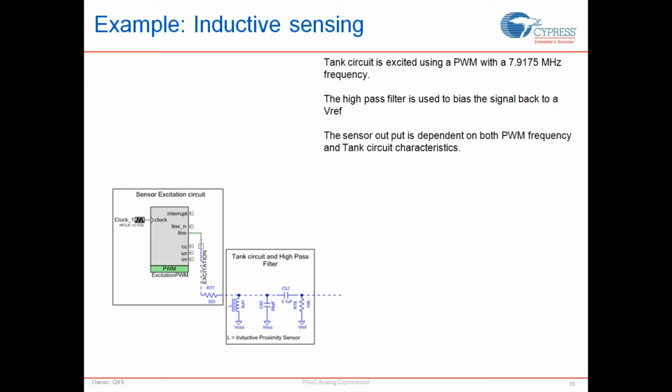So I want the variation from the 8 megahertz signal to be as minimal as possible, so that my down-mixed output is a really low frequency that I can measure using my ADC in an averaged mode and still get the most resolution out of it. So that's the objective. That's why you want a fractional divider, so that you have a small, fractional variation from your down-mixing signal.